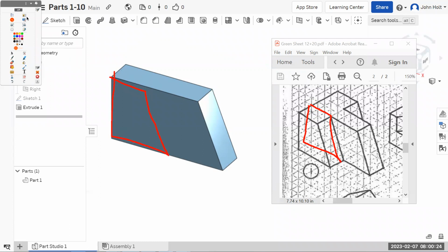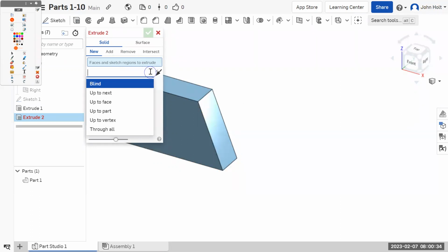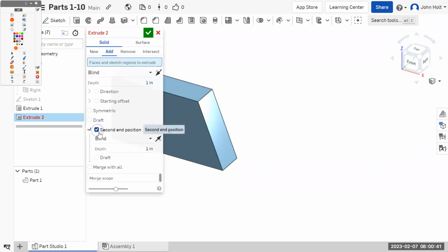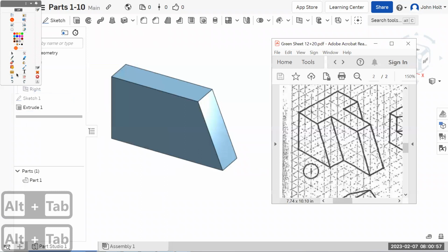And we should be able to, hold on, let me first check that Onshape has this feature. Find, add symmetric. No, I want asymmetric. And we'll go 2 this way and 4 that way. I think this will work. Yeah, it'll work. So what we're going to do is do a 2-direction extrusion.